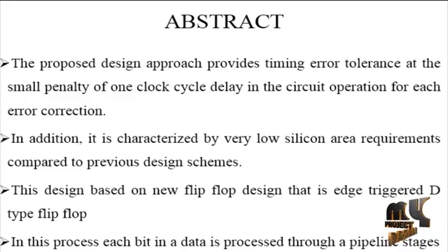In the circuit operation, for each error correction, the main objective is to develop a low-cost multiple timing error detection and correction technique, which is based on a new flip-flop design. In addition, it is characterized by very low silicon area requirements compared to previous design schemes. This design is based on a new flip-flop design, that is the edge-triggered T-type flip-flop. In this process, each bit of data is processed through pipeline stages.